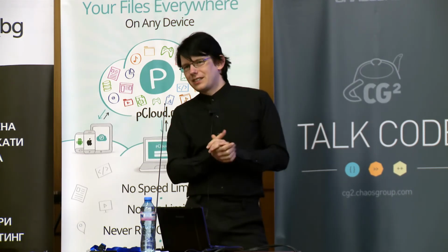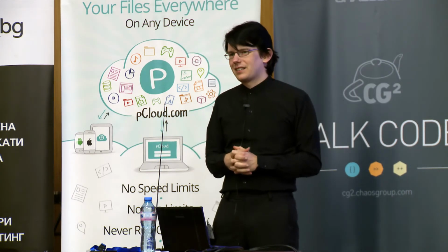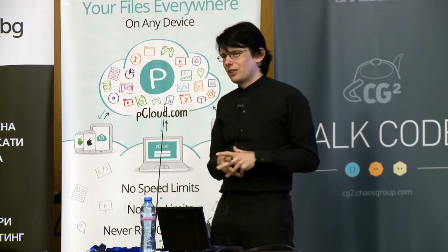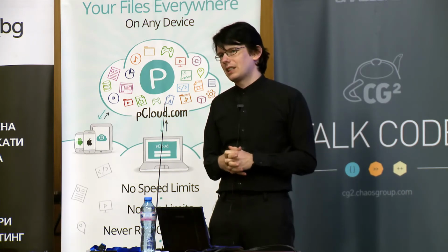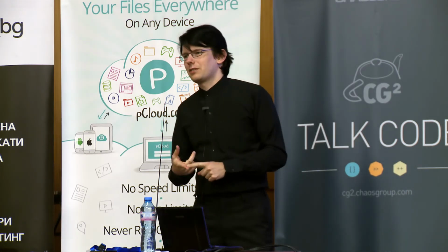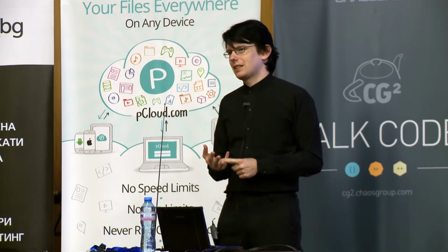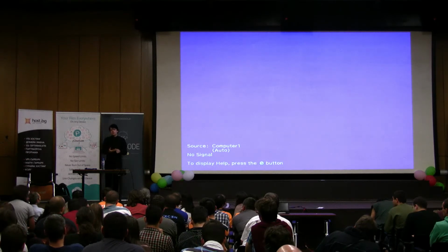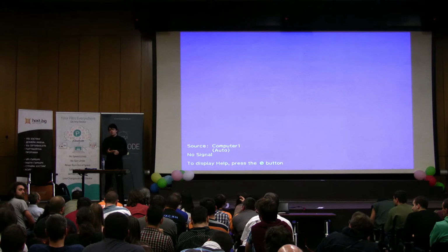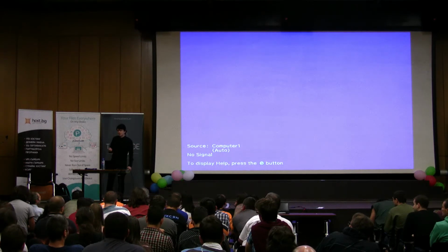One other interesting system that you can listen into, you need a satellite dish for this though, is the Thuraya satellite telephony system. There's an Osmocom project called Osmocom GMR by which you can receive the satellite communication. And the encryption has been broken for several years. The voice codec has been reverse engineered. And the interesting part about Thuraya satellite phones is that by the protocol specification, every phone that makes a call must transmit its complete GPS position at the point you attempt to make the call. So the call cannot be made unless you include the full GPS position of the phone.